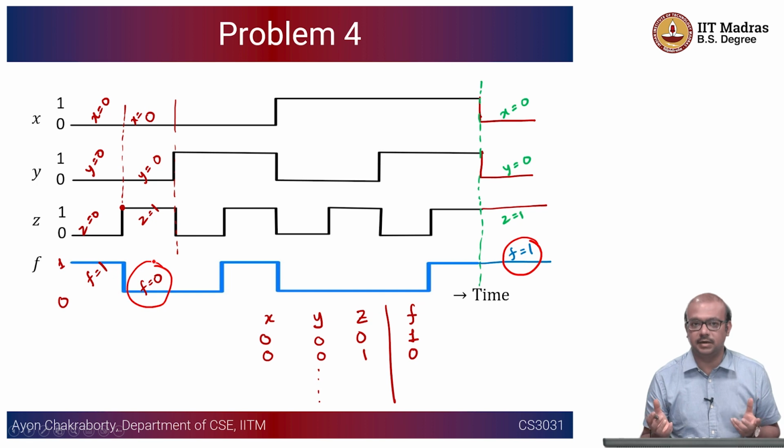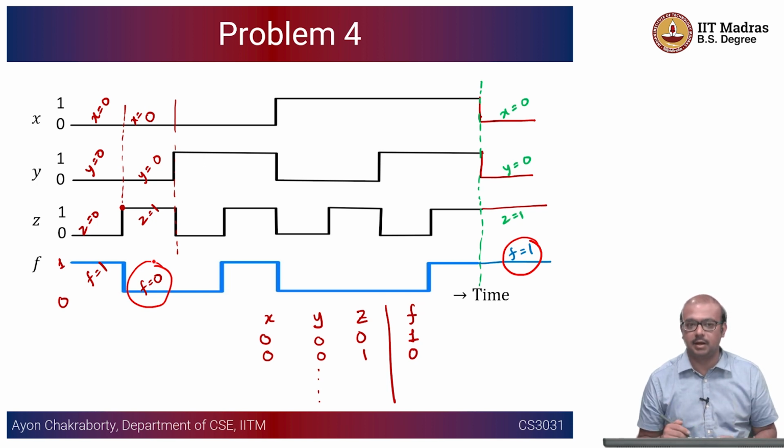This is inconsistent. Okay, so whoever is giving you the timing diagram, this is a wrong timing diagram because the functional specification itself is ambiguous. Okay, this cannot be the case. For the same inputs, you are going to have the same output every time. Okay, you might face this kind of a situation and you have to report that the timing specification is ambiguous.